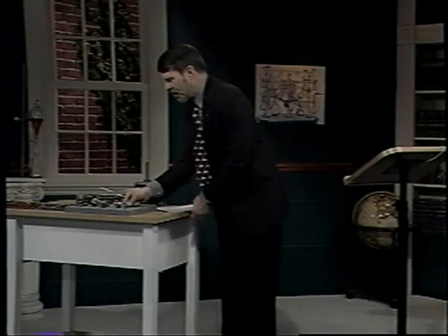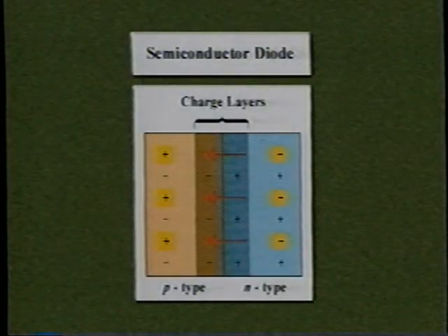Now, think about what happens in a situation where you have this sort of arrangement of semiconductor materials. If electric current flows into the negative side of a diode, it wants to flow right on through to the positive side because negative electrons are attracted to the positive end. In fact, the resistance is almost zero in this direction. But if you have electrons flowing into the positive end, they stop dead because negative electrons don't want to go towards the negative side of the diode. And the resistance in that direction is almost infinite. What you have then is a one-way valve for electricity.